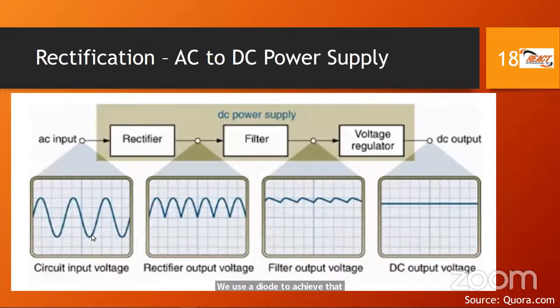In terms of converting AC to DC, because some devices need DC as opposed to AC, you have a power supply that delivers DC, or direct current, in the output. So it starts with AC. When you plug into your wall outlet, you're getting AC, or alternating current. But we have to get DC in the end. It has to be nice and smooth and positive and steady. But we have to rectify first. When we rectify using a diode, we will get pulsing DC.